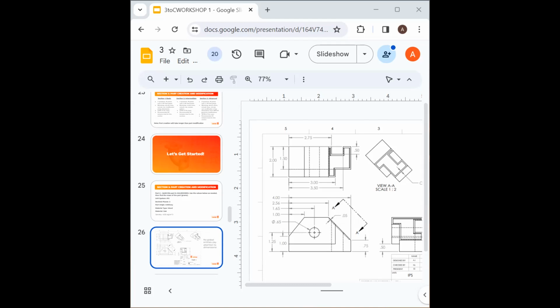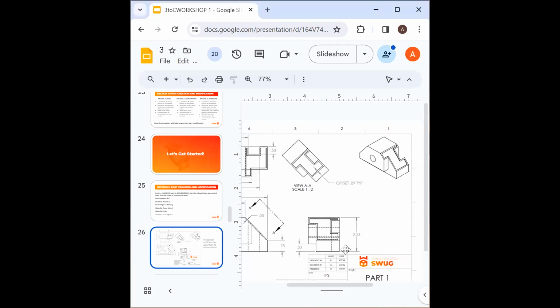Okay, that part's done. Now I'm going to go over to this specific corner, and I'm going to notice that I'm missing one box of the corner, which means I'm going to have to cut that out. So I'm going to orient myself to here, and create a new sketch on this specific base. Because this one already follows these lines, all I have to do is dimension how big I want it to be.